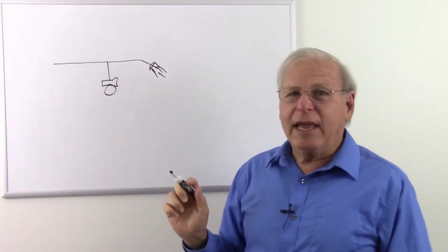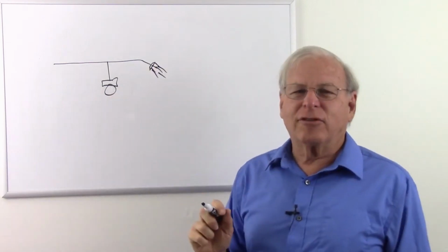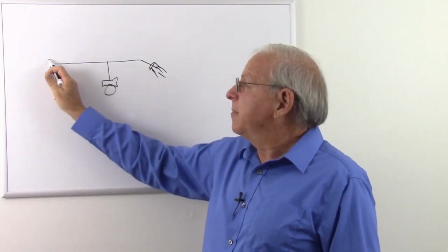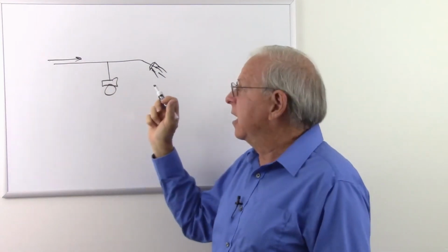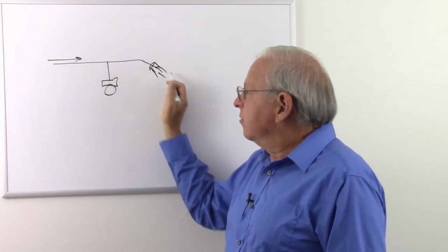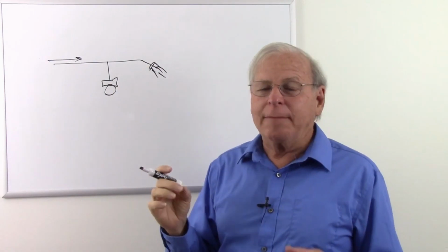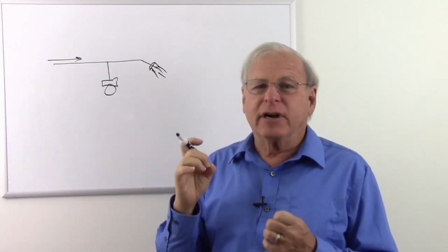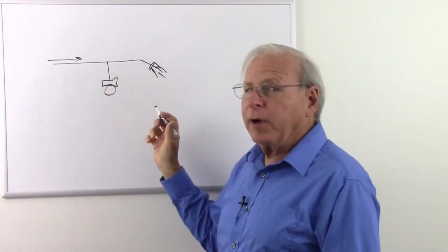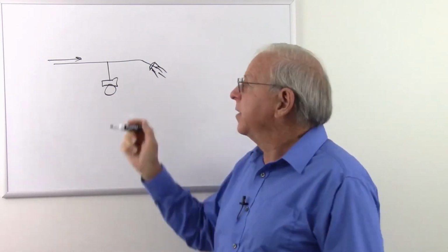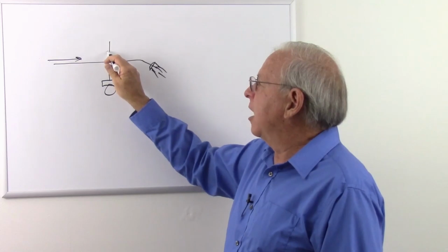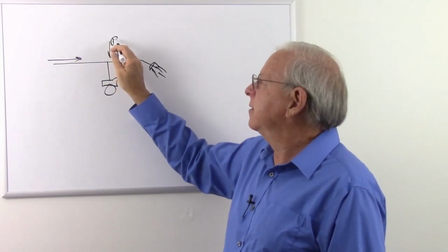Okay, so somebody is taking a shower and somebody comes and flushes the toilet. Well, this pipe can only allow so much water to come into the house at a time. And so if you try to use the shower and the toilet at the same time, it probably can't deliver enough water to service both. So what's going to happen? Something's got to give, and what gives is pressure. So what happens is the pressure drops in the cold water line.